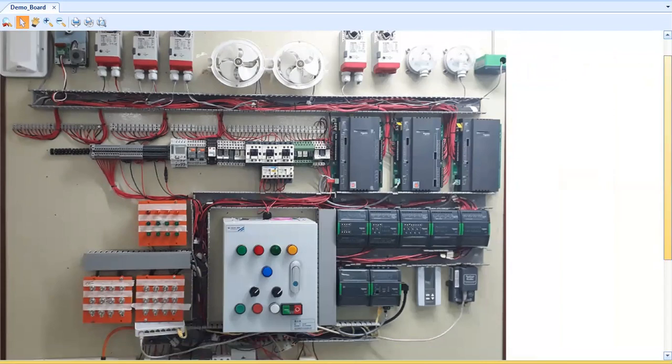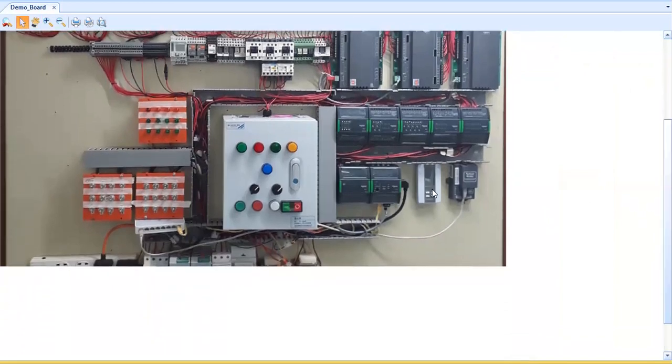Now, this automation server, as you can see here, I have one Cat6 cable that is connected to the switch. So this yellow cable is connected to my automation server. Then this network switch will be connected to my front-end computers, like my server and my workstation. So we are communicating over the TCP/IP protocol, transmission control protocol, internet protocol.